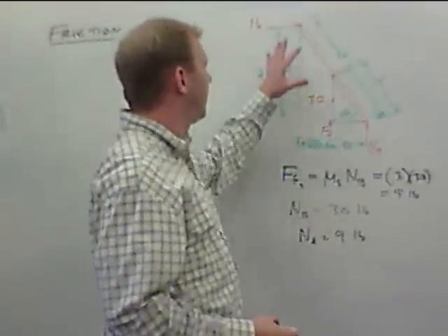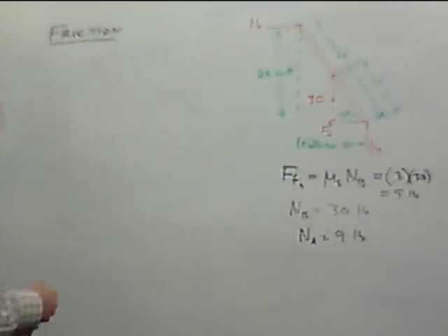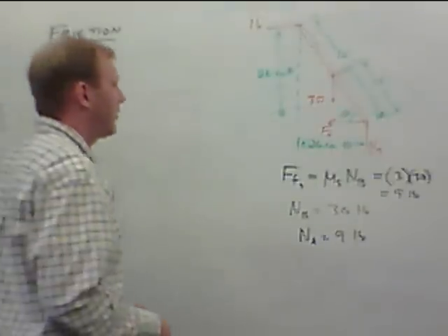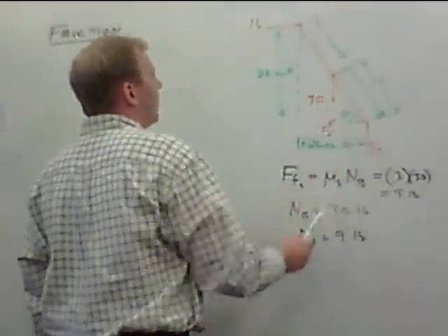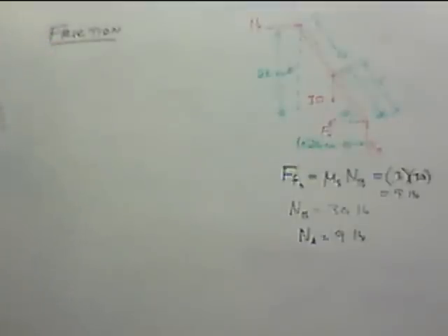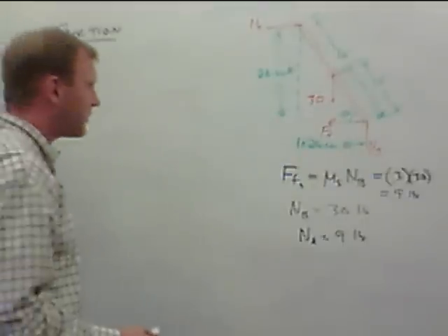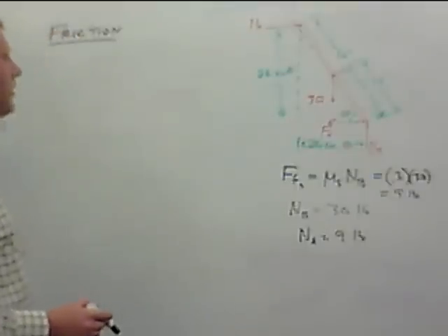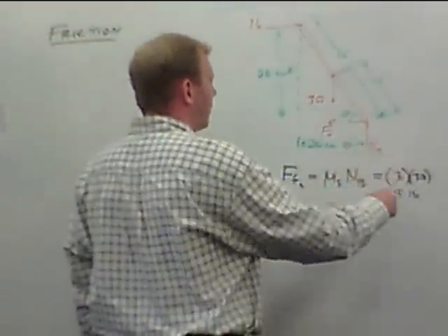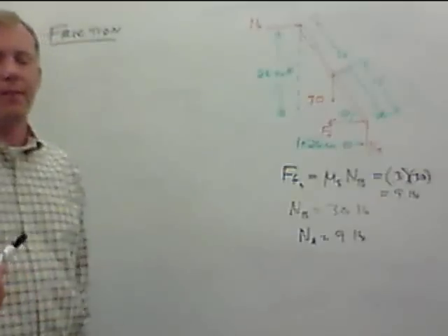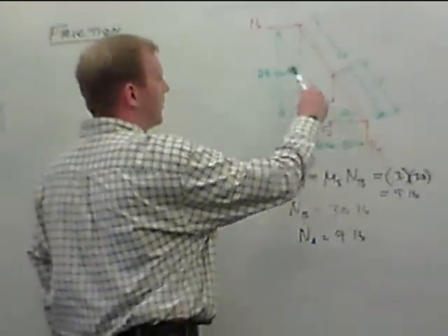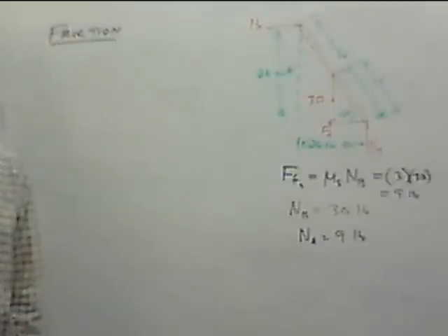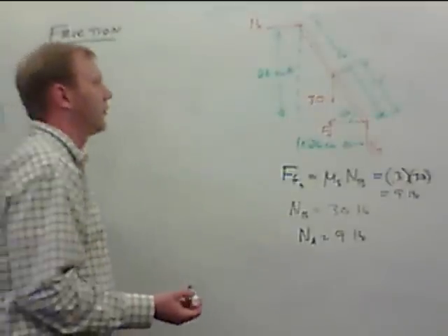We now know all of these. We've now been able to determine what all these forces are. The question is, how do we get theta? Well, theta is going to come from the summation of moments in this case. Because these forces fully meet the conditions for equilibrium of forces. We don't know that they've met the criteria for equilibrium of moments.